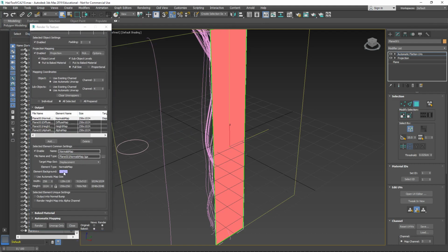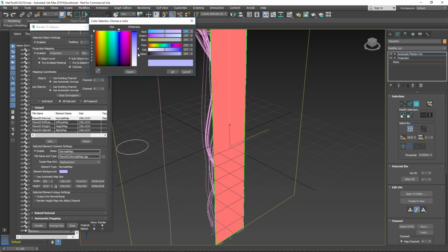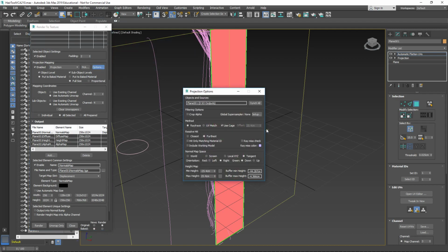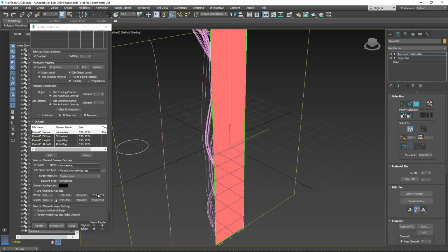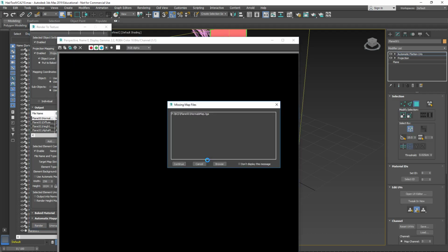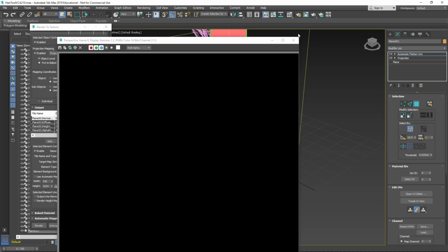The other thing that I must remember is to make sure that background is completely black, and make sure that under options, under mental ray check, you get rid of the mental ray check. Otherwise it ruins your color scheme. It paints red over your normal maps and things like that. Right, hopefully now it will go away and render. Why is it still rendering to the wrong place?